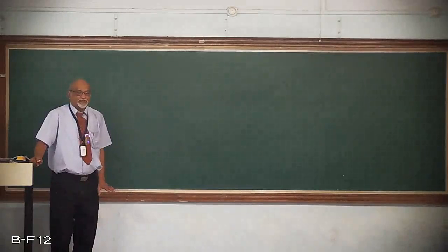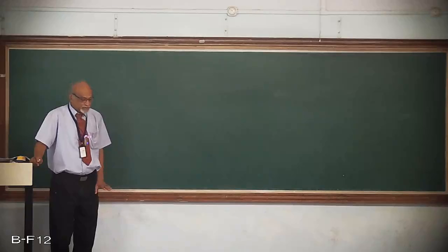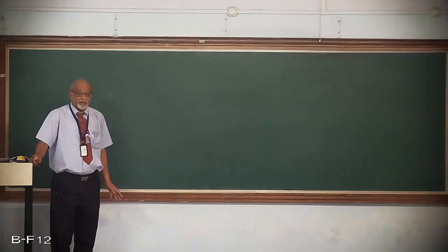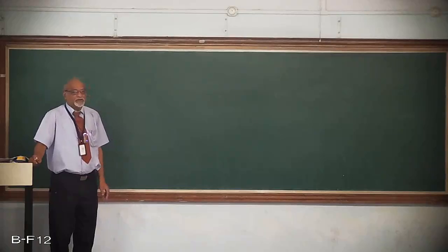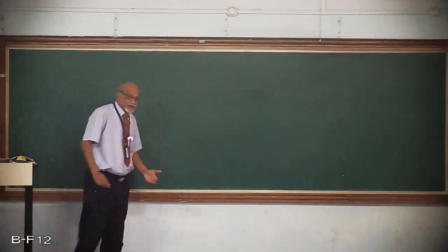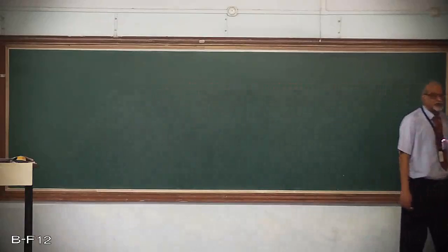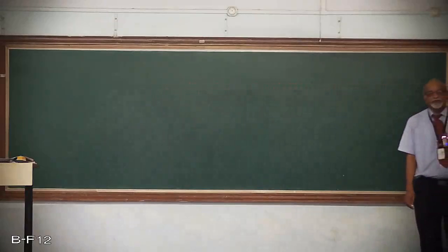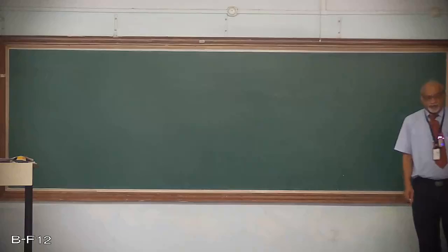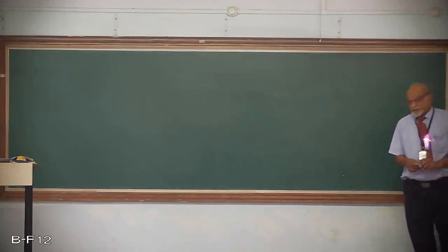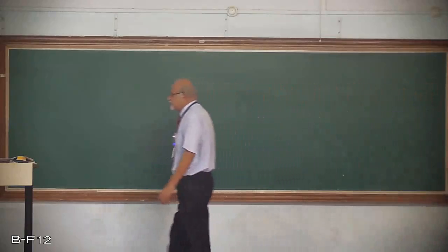In place of NP chart, you can use P chart, no problem. But you cannot use P chart in case of C chart, or you cannot use NP chart in case of C chart. Between U and C chart, always the U chart can be used in lieu of C chart, but C chart cannot be used in place of U chart. So first we need to think and categorize which chart is to be used. So let us take up this example and then see.